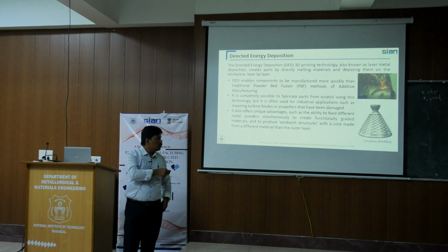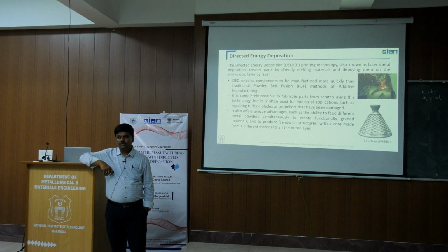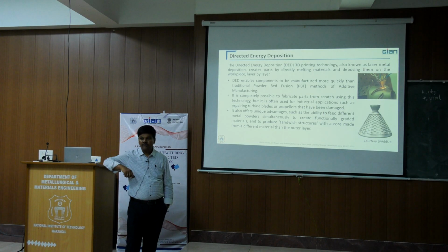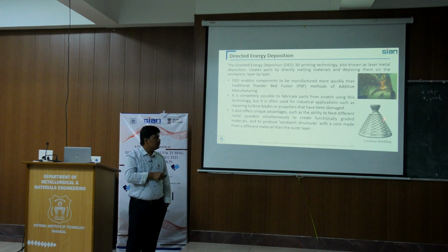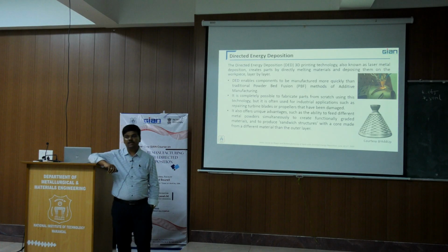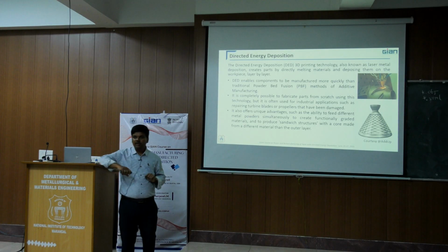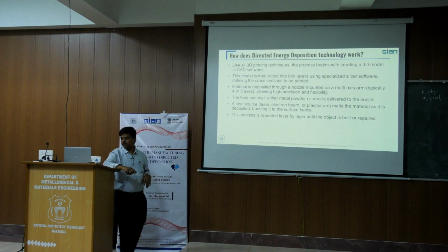Then I need to go with our laser DED process. One of the beam technologies that they have now added. They made a cold bed manufactured component along with the additional features. If you see, these are the features which are added by the laser DED process. Means any kind of existing components we are able to repair, or we are able to add additional structural aspects, additional features. It can be possible by the laser DED process also.